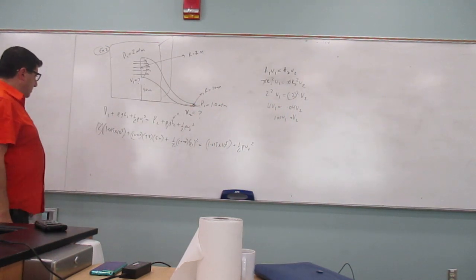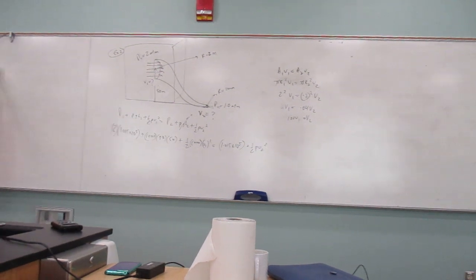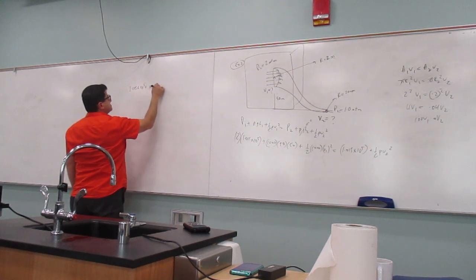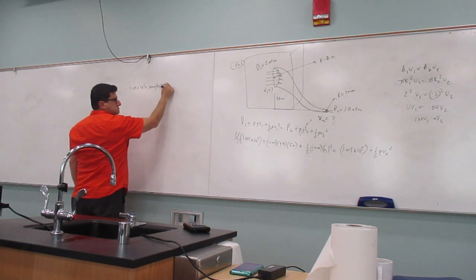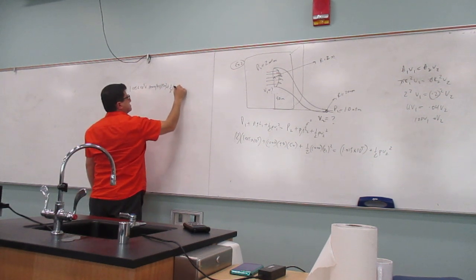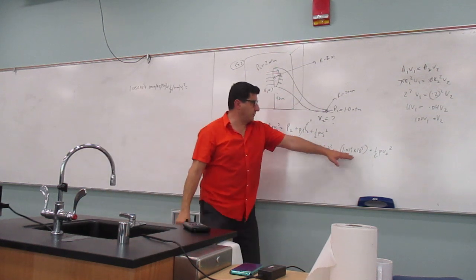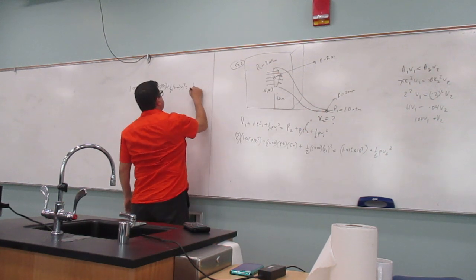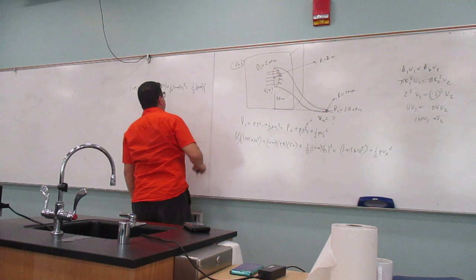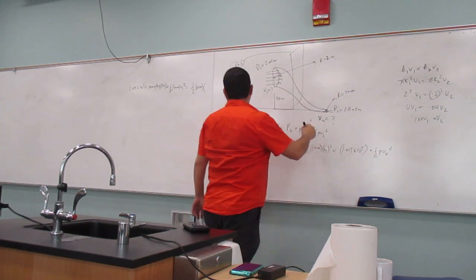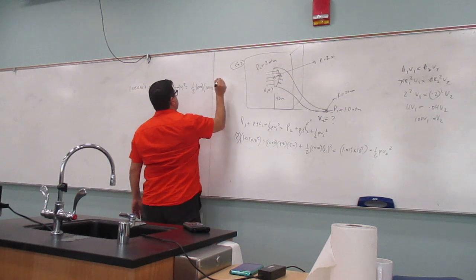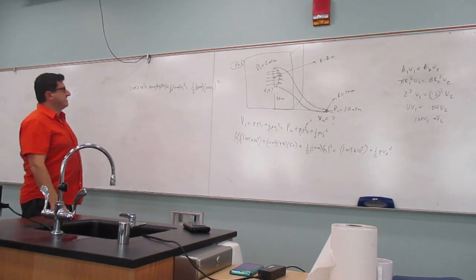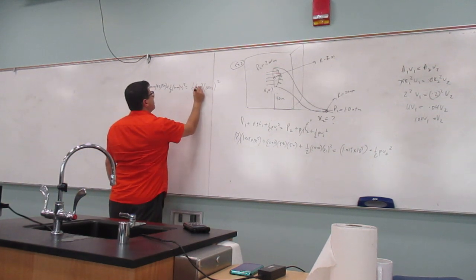So we could take that and bring it over here. I brought this pressure here and subtracted it from here. Then over here I could put half density of water, V2 is going to be 100 V1 quantity squared. Now you can solve it. Divide everything by 1,000 if you want.